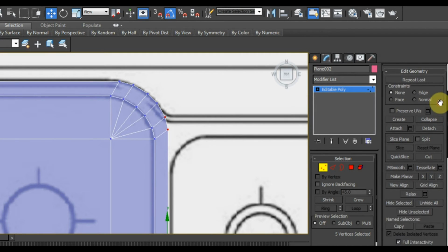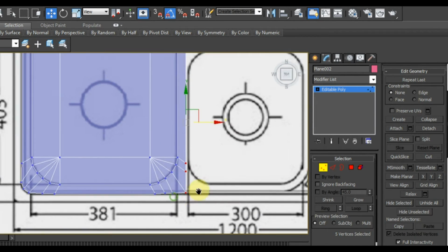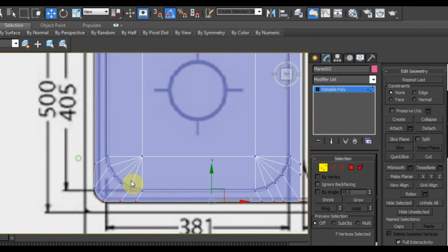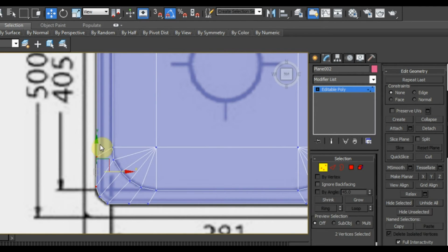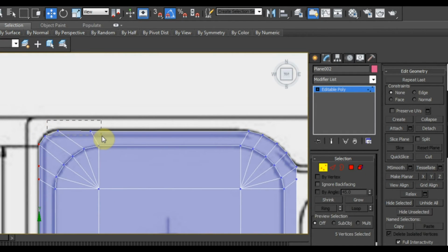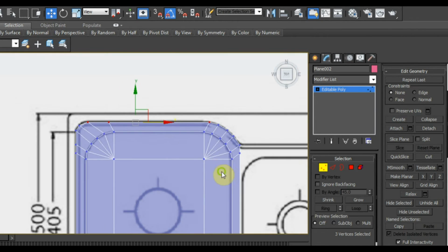And if we go down to the properties window again, we can click on this thing here where it'll straighten everything up in the X, Y, Z coordinates. So we'll select X, and as you can see it's moved them all, and now all in a perfectly straight line. We can do the same here with this one, and we'll press the Y key. As you can see, they're perfectly straight, and we can do that here. We'll hold down the control key, select them all, and click on X, and we've straightened up. And we can do that with these top ones, and we'll click on Y, and you can see it's perfectly straightened up there now, which is great.